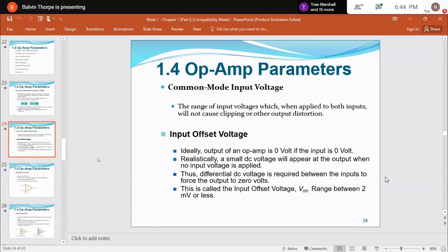So, sir, in a scenario like that, if you know the input voltage you will want to apply, you will take that offset and subtract it, or take the difference between it, and then apply it for the input? That's right. So that way, you will know what exactly your amplification factor is going to be. Because you are now taking, okay. So it's like saying, all right,